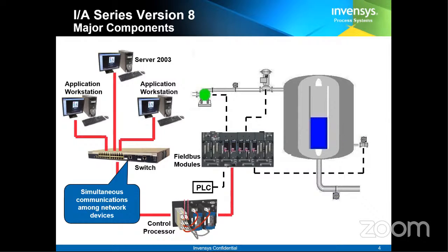To control the level in the tank, you have a valve. How much percentage it has opened now, what the transmitter value is showing, how much the level in the tank is. All this information you can see on the DCS operator screen. On whatever application workstations you have, there you have an operator window, and on the operator screen you can see all these values.